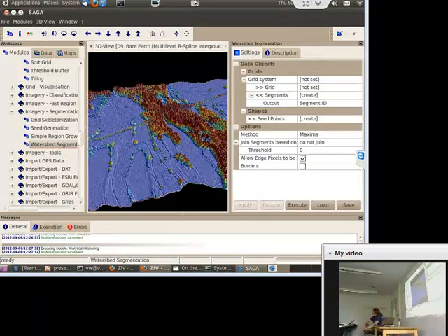In case the laser scanner is on the ground, is the structure of the file also .las, or do they generate a different structure file? In the meantime, more and more data is stored in the LAS format, but for the terrestrial laser scanner it is usually simply ASCII. So you get an ASCII file with XYZ columns, and then you convert it from there. You can import it from there too. But the LAS format is getting more and more prominent.